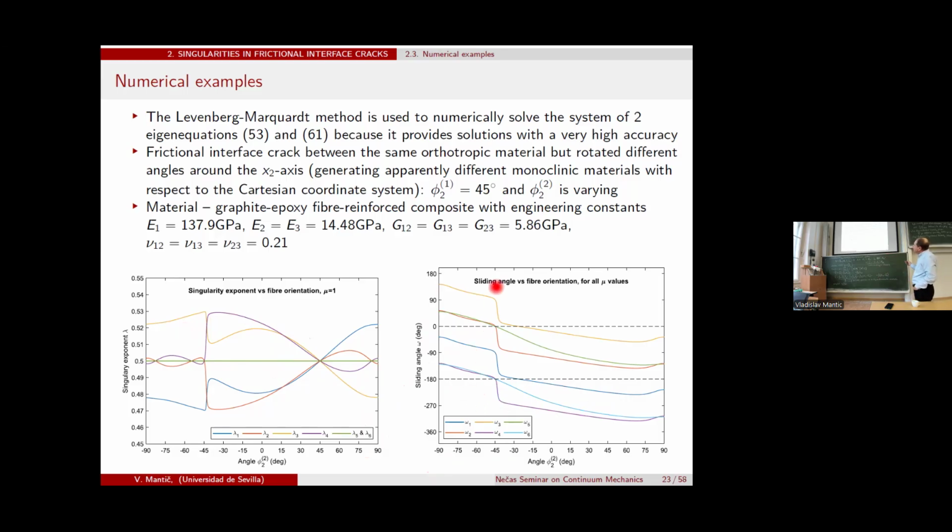You can observe that for eigenvalues which are not 1/2, the difference between the shear vector orientations is 90 degrees, and we have also observed that this shear stress vector angle is independent of the friction coefficient. It's curious because we don't see it in the equation, but we have observed it in our numerical solution. And the difference between angles of the solution corresponding to 1/2 is 180 degrees.